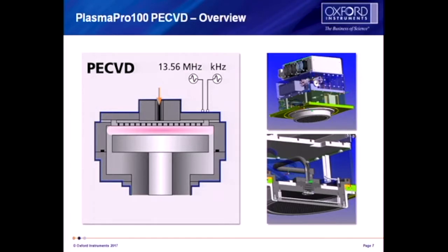uniformly heated. The second thing we have to increase uniformity is this shower head. Rather than the gases all being pumped into here and sitting around in the center and then slowly diffusing out in your chamber, we instead force them to come through the shower head, and that creates a really, really uniform gas distribution, so you get a much more uniform plasma.